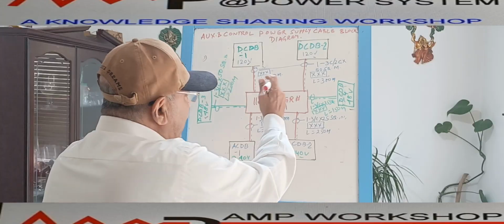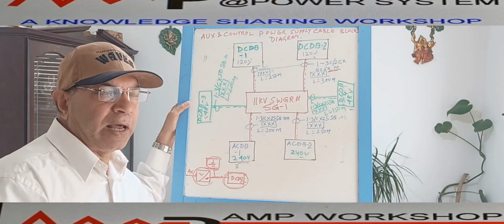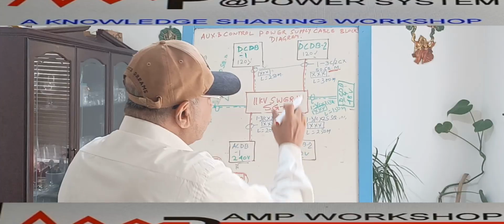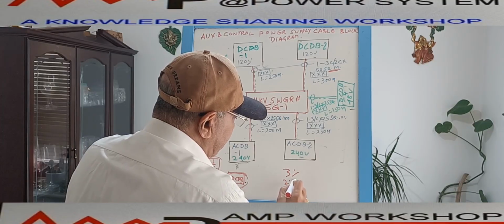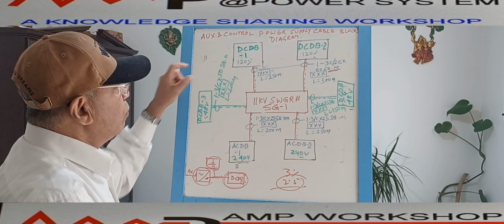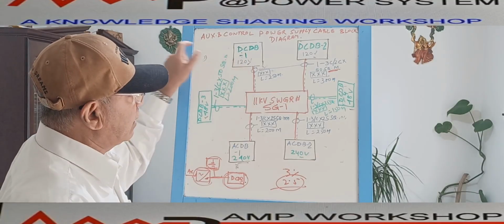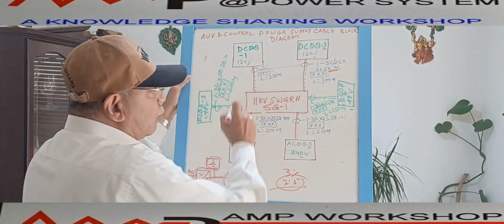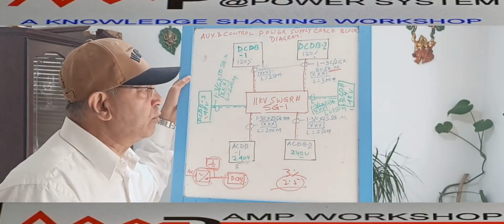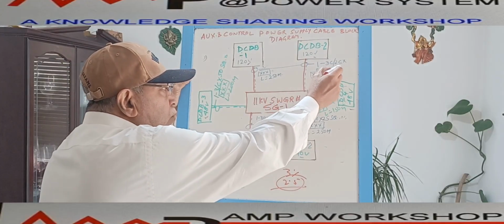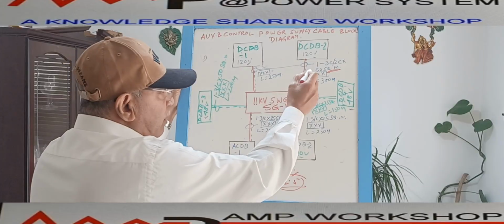That's why, when we are sizing this 50 square millimeter cable, we look into the voltage drop calculation very minutely. We try to calculate that the voltage drop should not be more than 3%. 2.5% is the normal; we calculate within 2.5%. With that voltage drop we size the cable. I have considered 50 square millimeter 3-core, or if you want to use 2-core, you can use a 2-core cable. That one number 3-core or 2-core 50 square millimeter XLPE cable is a 600 volt grade cable that we are using for this DCDB.